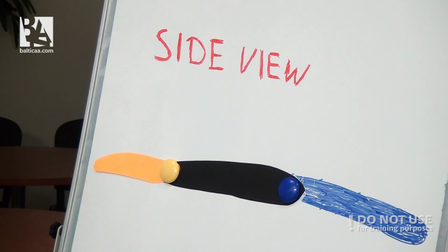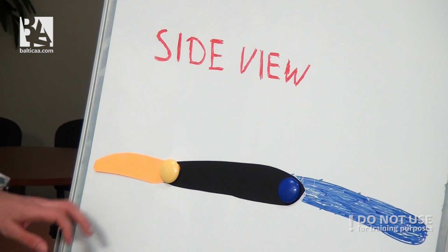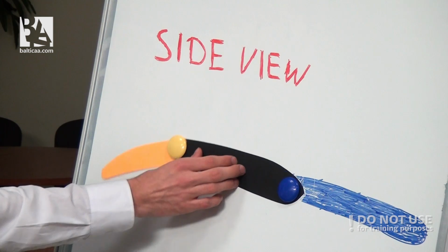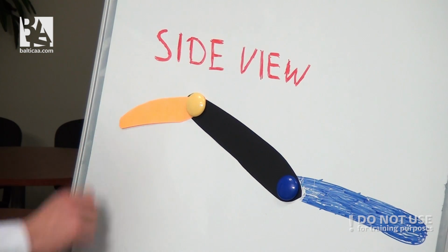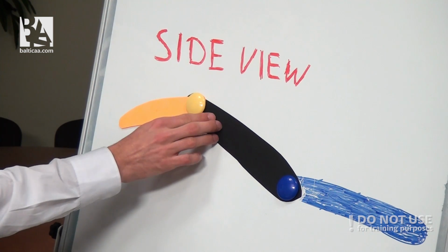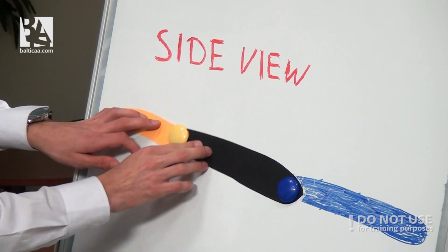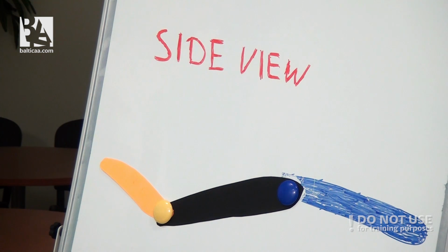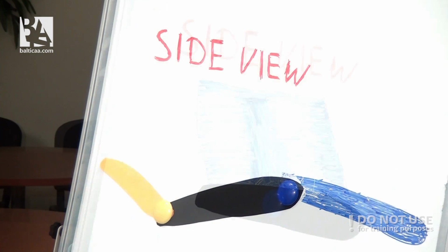If your plane is equipped with trim tabs, they will move in the opposite direction. If you want to trim nose up, the trim tab will move down and the elevator will move up. If you want to trim nose down, the tab moves up and the elevator moves down. The negative side is that you will have less control authority, more drag, and also a less CG range.